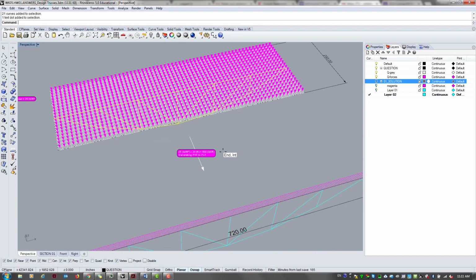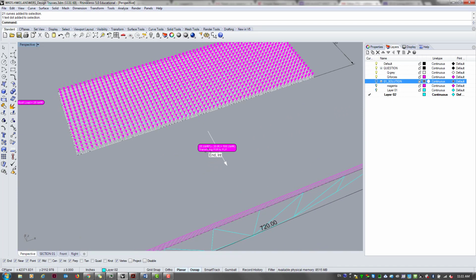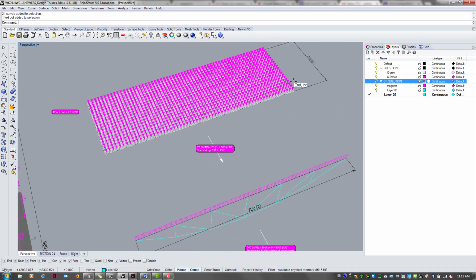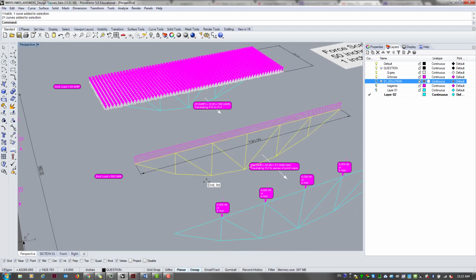So to convert that to pounds per linear foot, you basically take the width of that slab that this truss is taking care of. So instead of 25 pounds per square foot, you multiply that by 20, which is the width of that. Now it becomes a uniformly distributed load of 500 pounds per foot, right? So that's basically the uniform distributed load for each of these trusses.